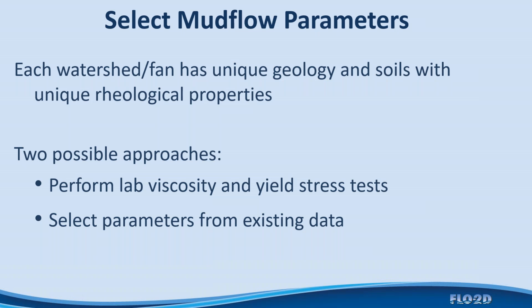fluid matrix, sieve out the cobbles, and you could leave some fine gravels if you'd like, or the sand material, and do these viscometer analyses, as I mentioned to you, doing 10 or so points in order to plot and get the slope of the line as a viscosity and see what the yield stress would compute out to be.